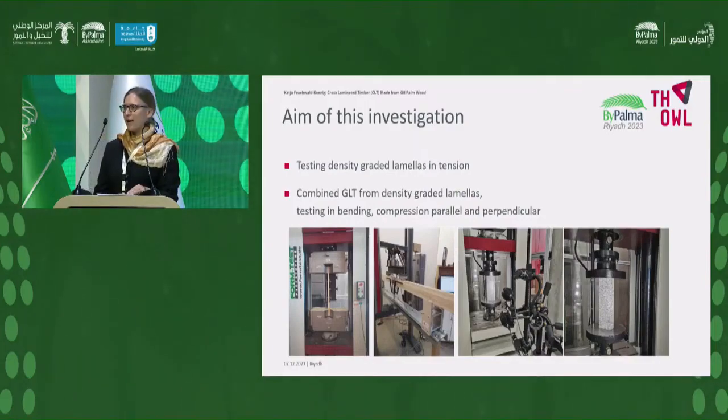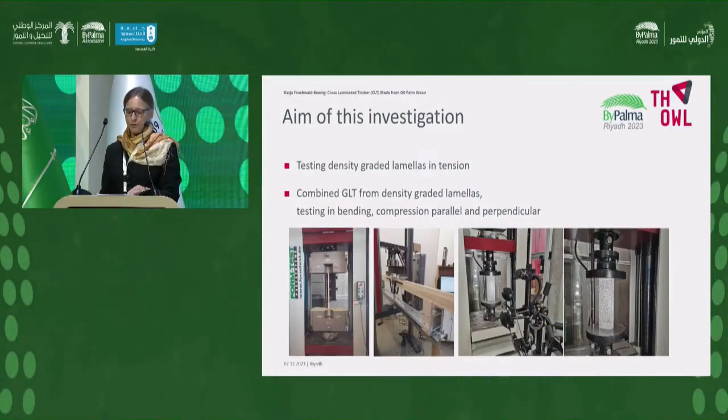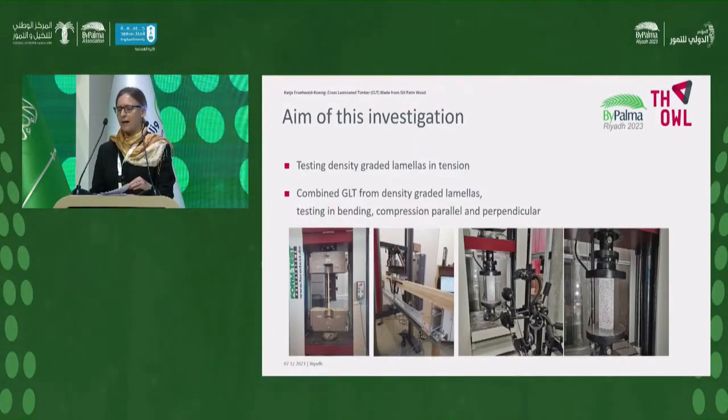Within the context of a research project, we tested glue-lam lamellae in tension parallel to the vascular bundles. We produced and tested combined glue-laminated timber from density-graded oil palm wood in bending and compression, parallel and perpendicular to the vascular bundles.